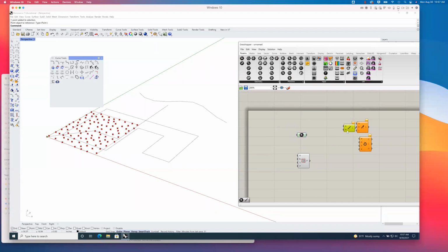Now let's say I want to make a line between this point and every point in this cloud, right? So if I just did 1 point and 1 point, I'd get one line out, right? That connects between the start and the end. But now, because I'm giving it a point here and then 100 points here, right, I'm going to get 100 lines out. There we are, right? So it's drawing a line between this start point and all of these endpoints, right? So I get 100 lines out.